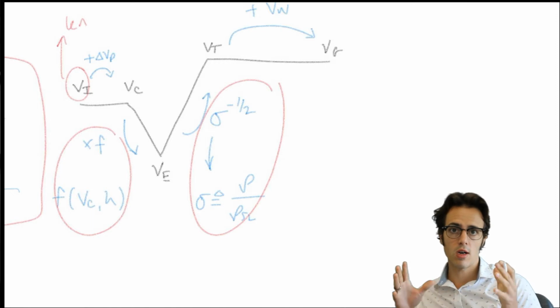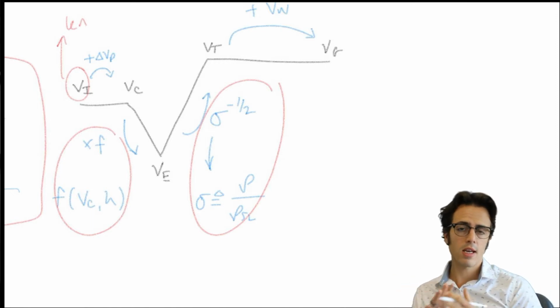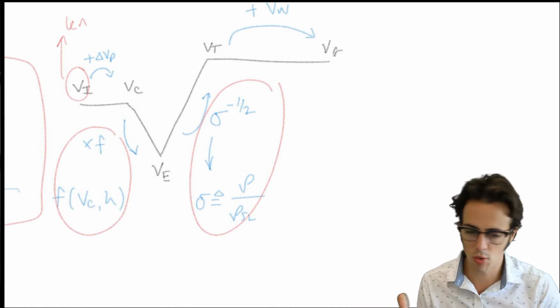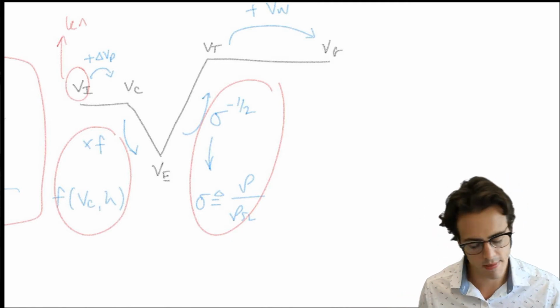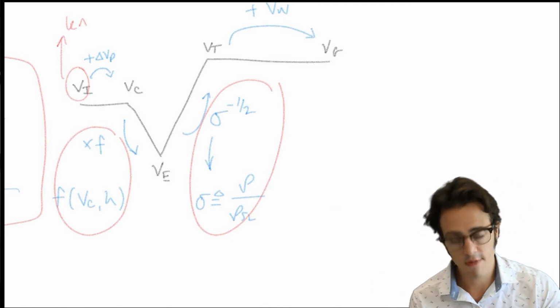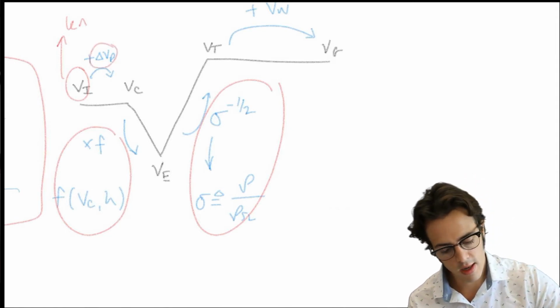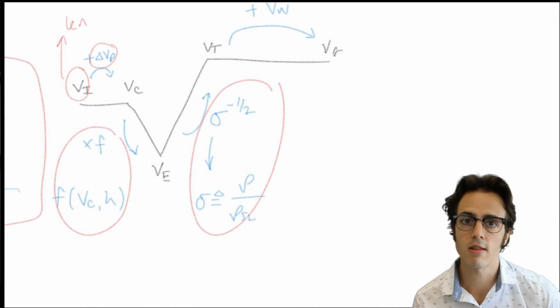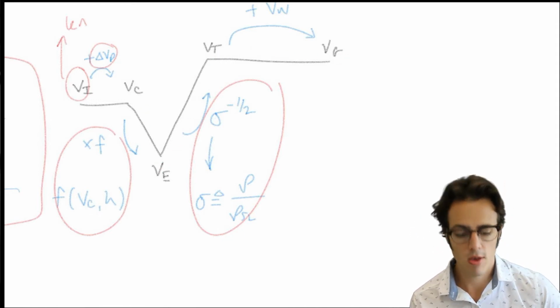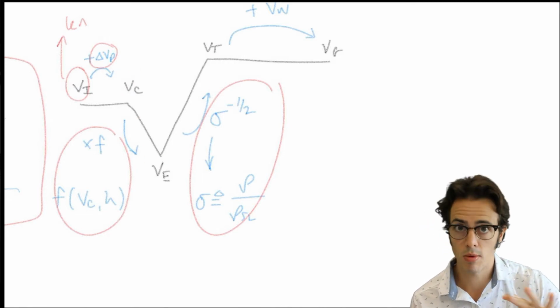Knots are a unit of speed that are typically used by airframers and is used all around the world to measure airspeed. So if we've got a VI measured in knots and we've got delta VP measured in knots, then our answer stays in knots all the way through this process until we get to the end. Okay? So keep it in knots and then convert it at the end would be my advice.